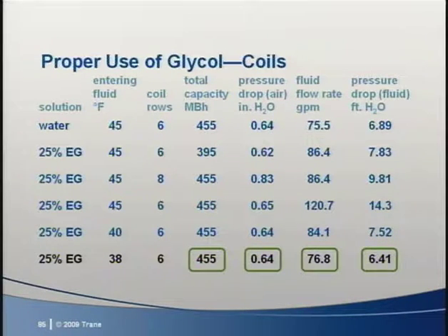Finally, a cold entering fluid temperature creates the opportunity to reduce the supply air temperature. Cold air systems can allow some combination of smaller air handlers, smaller VAV terminals, and smaller ducts, and/or reduce supply fan energy use. Producing a colder fluid temperature, however, makes the chiller work harder and use more energy. The key is to strike a balance between all the system components.